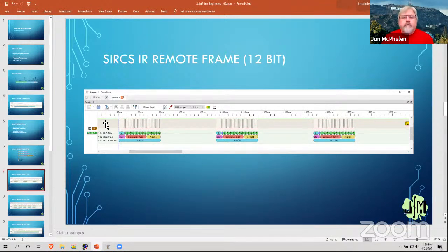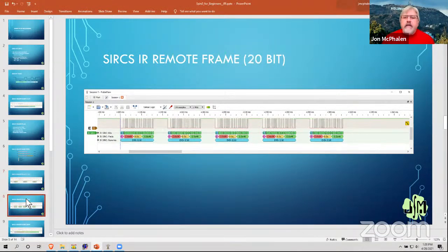And so from a safety standpoint, the end of this packet from the first detected to here is going to be 150 milliseconds. But remember, some TV remotes send 5 packets. So you'll see where that comes into play here in just a second. In fact, here's a capture from my DVD remote, and you'll see it's sending 5 20-bit packets.